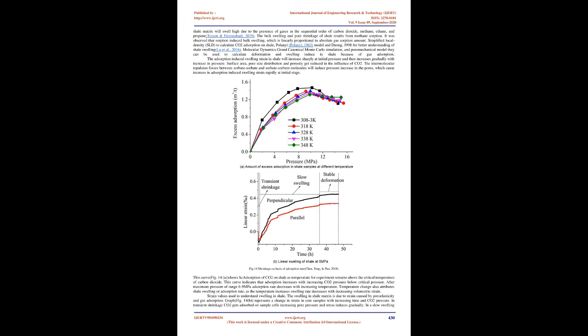As the moisture content in shale increases, it affects the performance of pressure drop. Due to the lower solubility of CH4 in water than that of CO2, CH4 sorption decreases in the moist condition in the presence of CO2. Effect of CO2 adsorption on petrophysical and mechanical properties of shale.